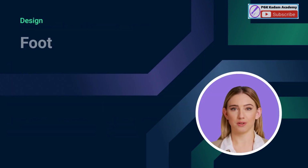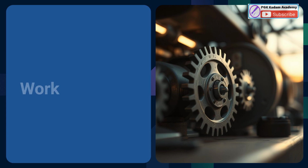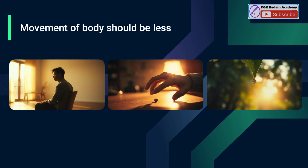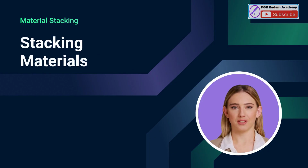Foot rests must be flat, and in movement design, symmetry of movements must be assured wherever possible. Work rhythm: symmetry of movements must be assured wherever possible, minimizing physical strain. Extra human efforts must be avoided. Movement of the body should be less. Minimizes body stress. Stress on body elements must be very less or minimum. All parts and materials must be clearly visible. Stacking of materials should not be risky.